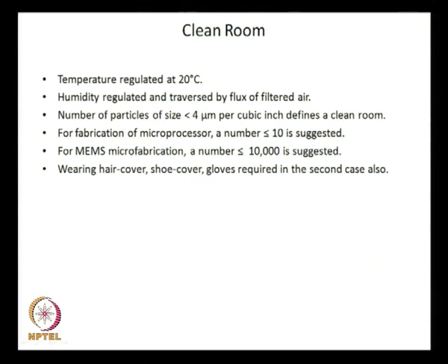One thing I would like to point out here is that typically in the replication method, when it comes to making a plastic MEMS device, when you make the mold, a clean room is a must, because you have to make a silicon master. You have to make a master which you either press as a stamp, or use as a mold on which the liquid molten plastic would be poured. When you make that master, it is important that you have the clean room, but when it comes to the replication method, the requirements are not that stringent.